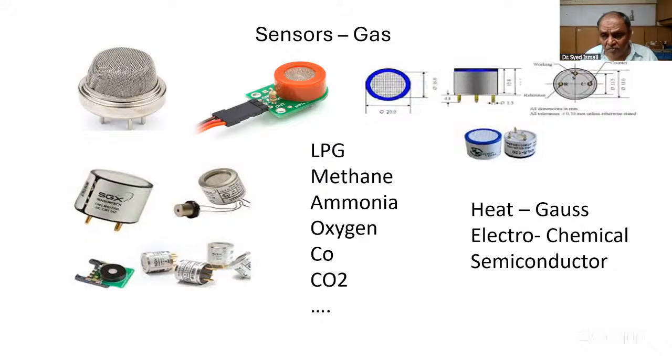So you have to refresh; you can easily find almost all types of gas sensors. But remember, certain sensors like CO2 sensors don't last very long. They last hardly a year or two, then you have to throw them out to get better accuracy. CO is easier; CO2 is a bit expensive to make. So you must know the difference, which sensor, how much reliability, how much accuracy you really want. For most of agriculture, we don't require very high accuracy. Even 10% accuracy, 20% deviation is okay most of the time. So we have to choose that type of sensor for that particular application.